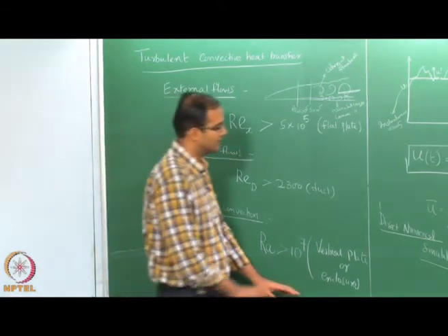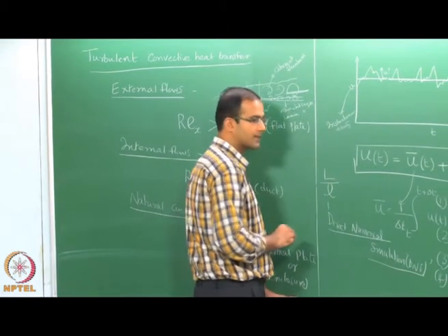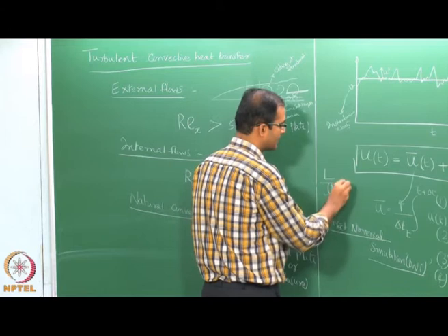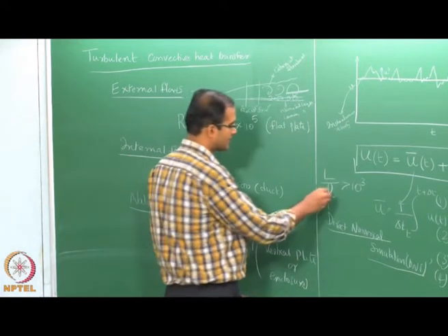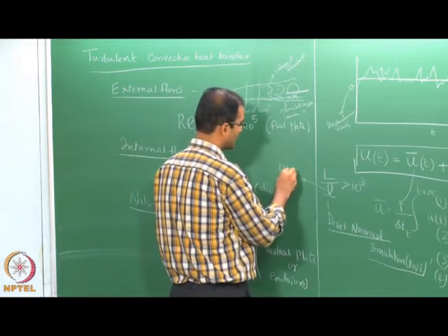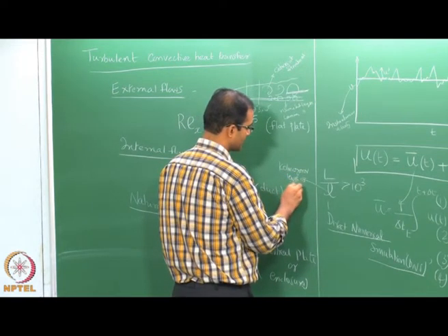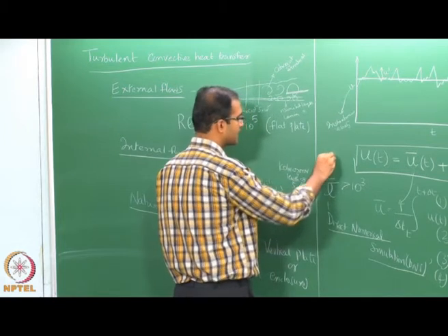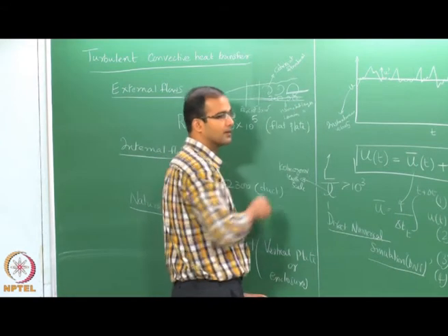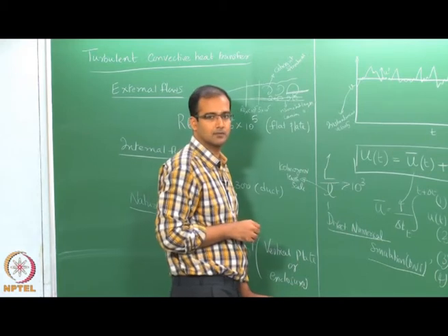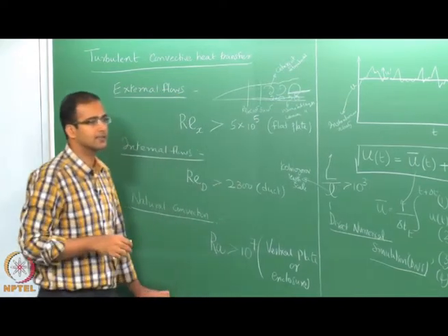because most of the times the ratio of the largest eddy to the smallest eddy can be greater than 10 power 3. Okay. So, the smallest length scale is called the Kolmogorov length scale. The largest length scale could be almost the size of, for example, here it could be almost comparable to the boundary layer thickness itself. Okay. The smallest length scale is the length scale before which it finally gets dissipated into heat.